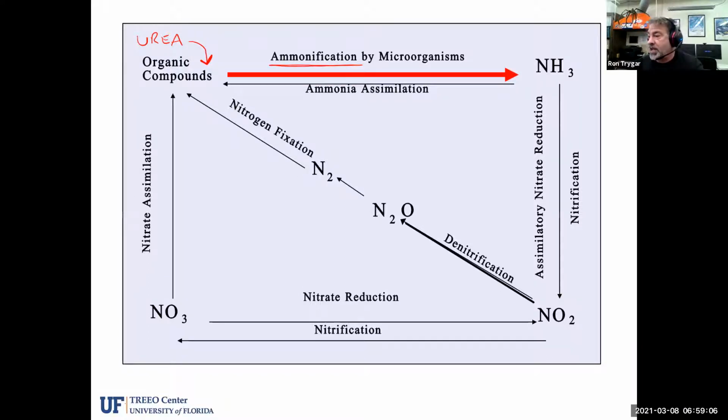So the first red line that you see here is the organic compounds flowing through the wastewater collection system and making their way to what we call the headworks of the treatment plant. So coming up into the headworks of the treatment plant, we have had something called ammonification happening. Ammonification converts the organic compounds into ammonia, but remember, it's not all going to be done. We're still going to have some organic nitrogen, I'm going to put ORGs for organic, entering the treatment plant.